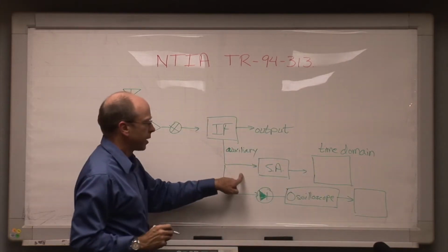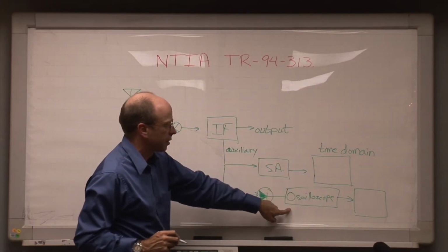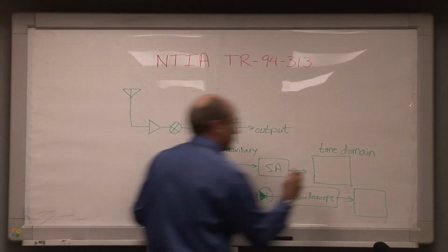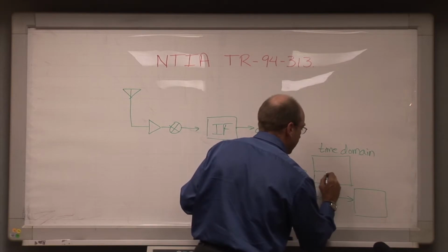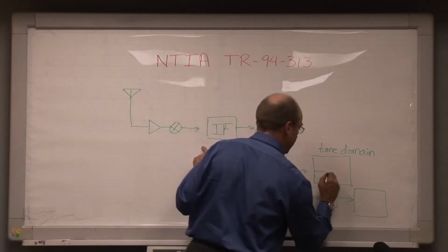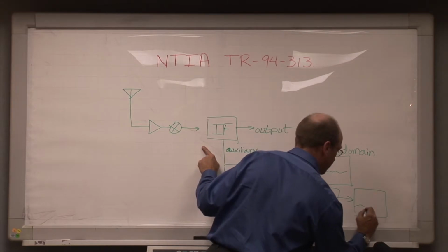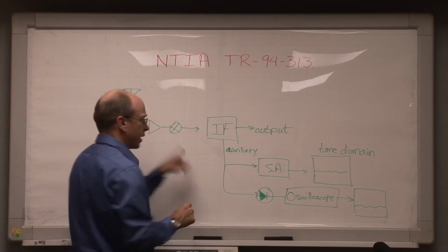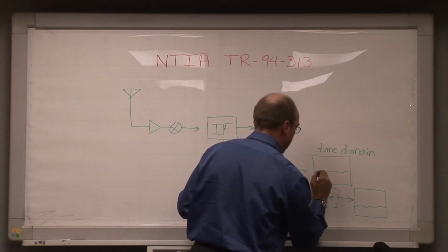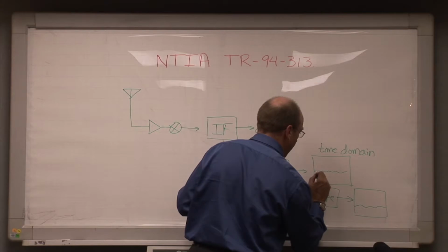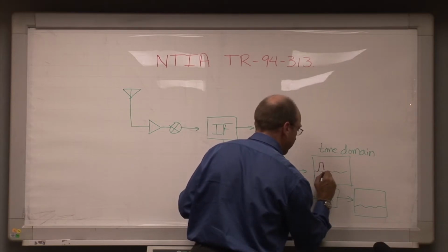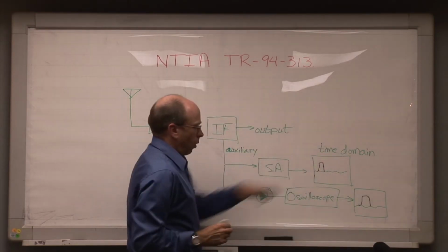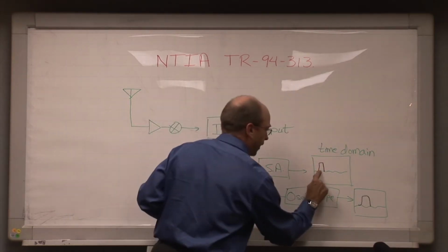Bear in mind that the spectrum analyzer in a certain sense is like an oscilloscope that works at a slower time rate, and which has a detector built right into it. And we're going to look at the desired signal level coming out of the IF, which will look something like this. Here it is on either of these two units. It looks like this. Desired signal. And every so often, a front-end overload is occurring when this receiver is hit by the emission from the transmitter in question, which looks like that.